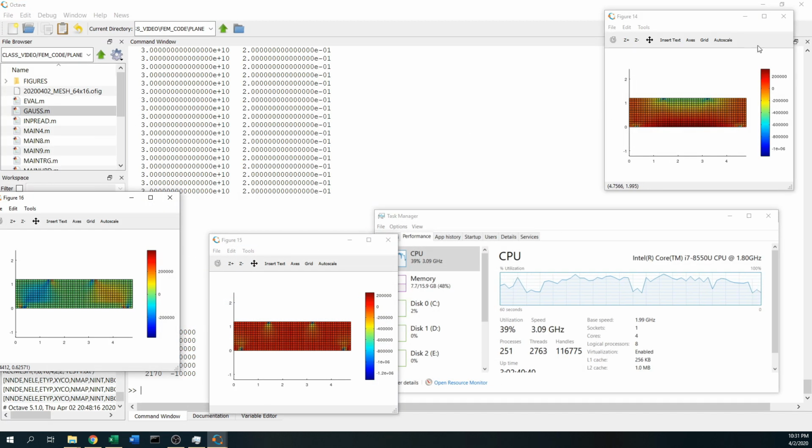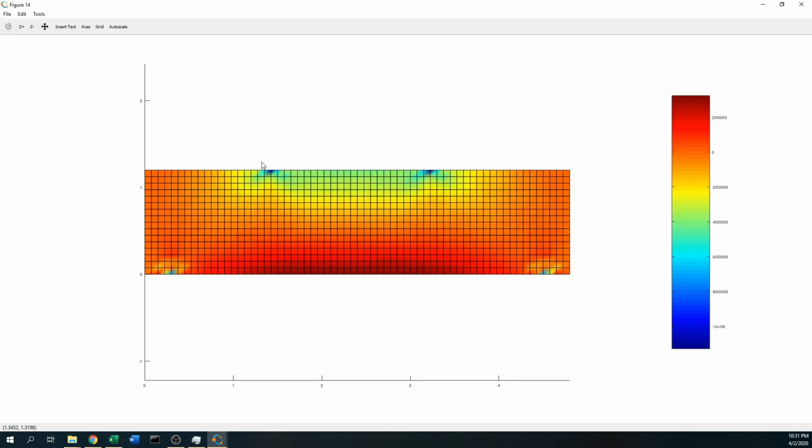Stress, I told you stress wasn't supposed to be calculated from just one rigidity matrix, because we have more than one material, so it will actually need to pick up the elastic modulus for steel to drop in here in order to find the stress in steel.